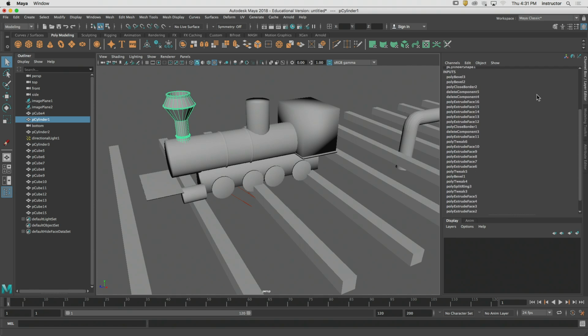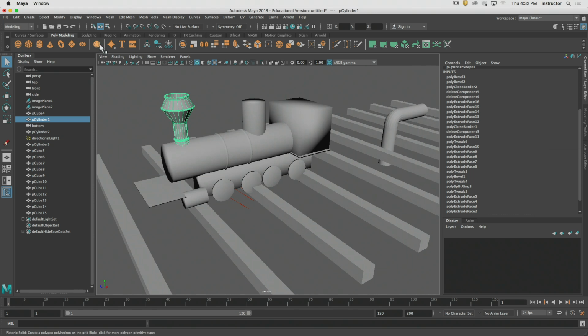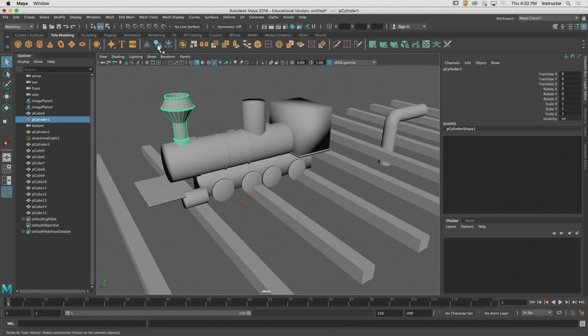That's going to get in the way after a bit. If Maya starts to chug, delete your history, okay? It's a lot of data that it's trying to manage on the back end of its database, and sometimes it doesn't do a real hot job with that, so just deleting your history will clean things up and make it more efficient. It truly makes it independent.